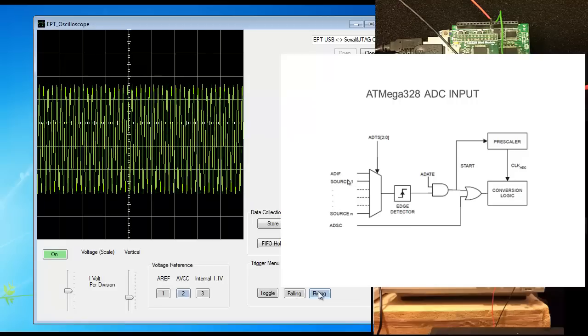The source 1 input is from our analog signal to be displayed. The signal is selected by a multiplexer and is directly applied to the conversion logic. This logic is directly controlled by the ADC clock. Changing this clock value changes the amount of time between conversions, and it ultimately controls how fast of a signal can be applied at the analog input.